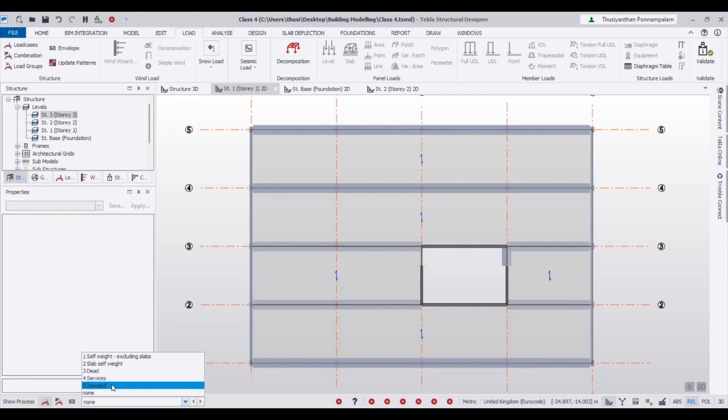If you refer to the EC1 code, for an office building your live load is between 3 to 4 kPa, or 2.5 to 4 kPa, it's different. So I'm going to use 3 kPa. This one is called a live load, or the easier terminology, an imposed load. So the imposed load is 3 kPa.